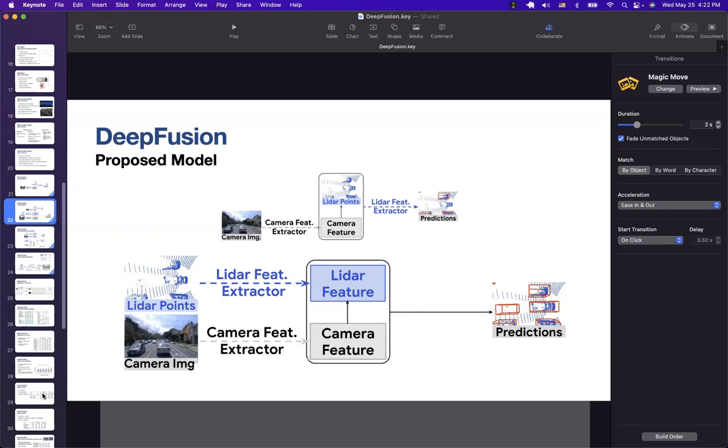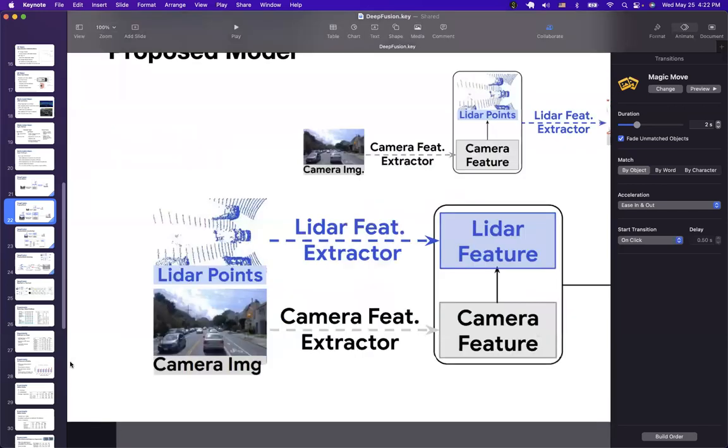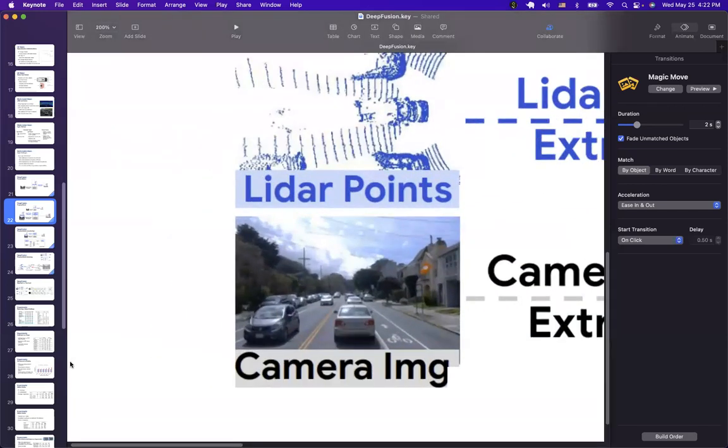Yeah, thank you. For this question, I have some follow-up comments. Before, we mentioned we can have RGB images with depth, right? Actually, this kind of RGB image with depth comes from the combination of the camera image with the 3D point cloud data. By combining them together, we can create this RGB image with depth. The main reason is that if we only use cameras, we can get the RGB values, but there is no way to get the depth.